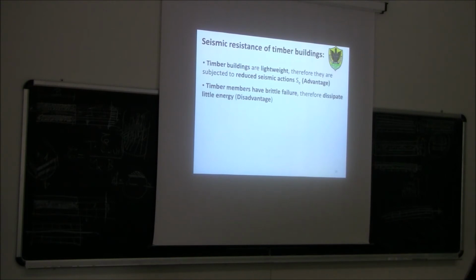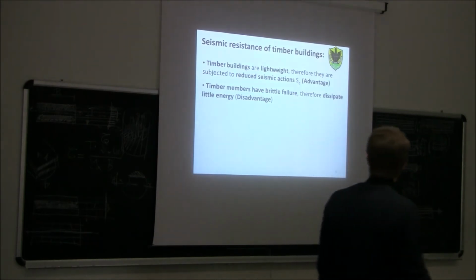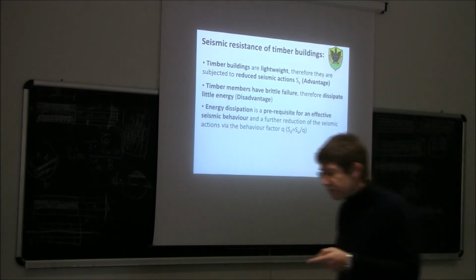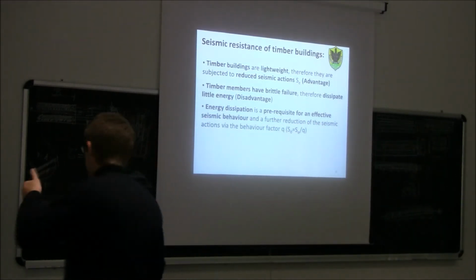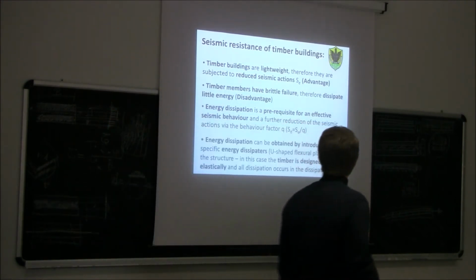If we started to do cyclic tests on this beam, we would have found very little energy dissipation, and this is a disadvantage. In fact, energy dissipation is a prerequisite for having an effective seismic behavior and for using a behavior factor, so for reducing the value of the seismic forces applied on our structure.